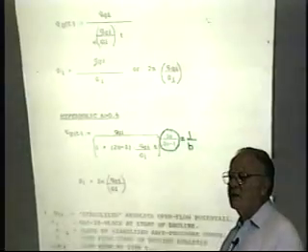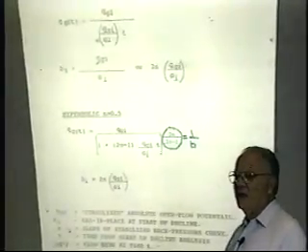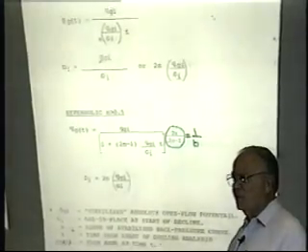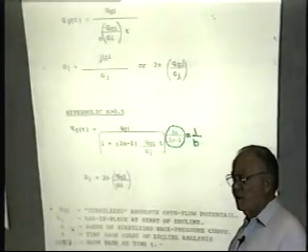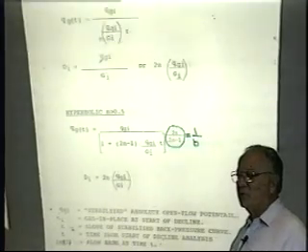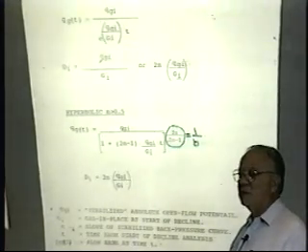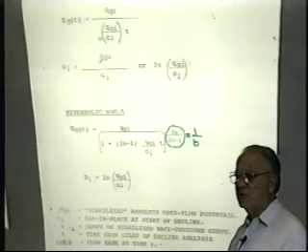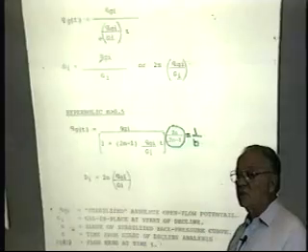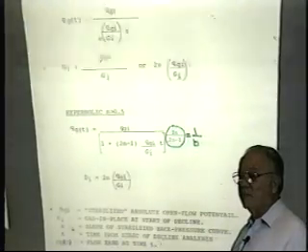It really simplifies the derivation. I already told you, if you're going to worry about it, yeah, but I'm not going to flow against a 0 line pressure. As a prudent operator, you're going to flow against the lowest flowing pressure you can, and if it's a function of a difference in pressure squared, whether it's 0, 100, 200, or 500, the rate's going to be virtually the same, okay? You have to understand that.